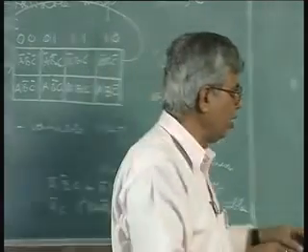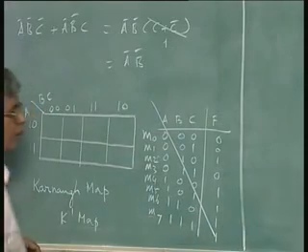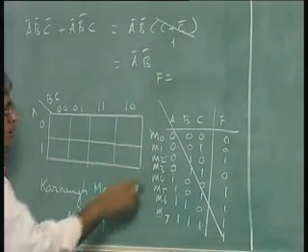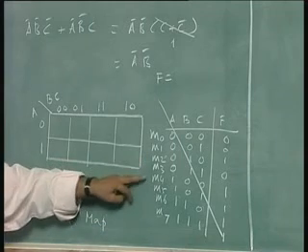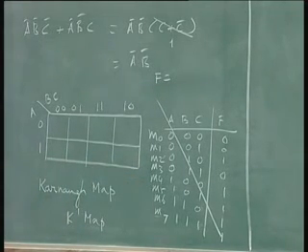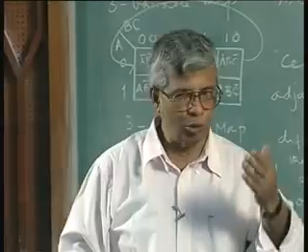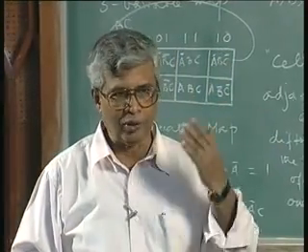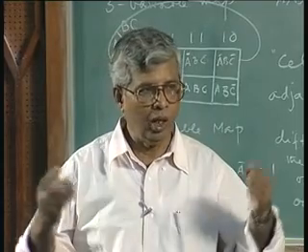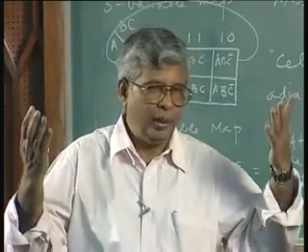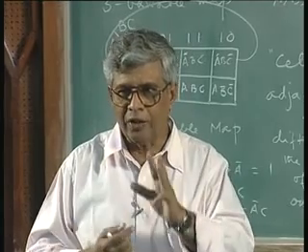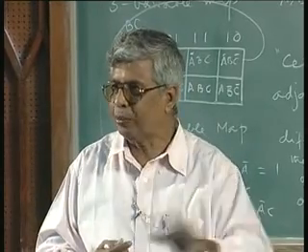If that information is called the truth table, you list all the input combinations and also list those for which the output is 1. So instead of saying all this in such a big way, can I not simply say this function f has output 1 for m2, m4, m5, m6, m7, because you know what m0 is for 3 variables. It has to be a bar, b bar, c bar, or p bar, q bar, r bar, or x bar, y bar, z bar, whatever. It doesn't matter, but as long as there are 3 variables, only these 8 combinations are possible.